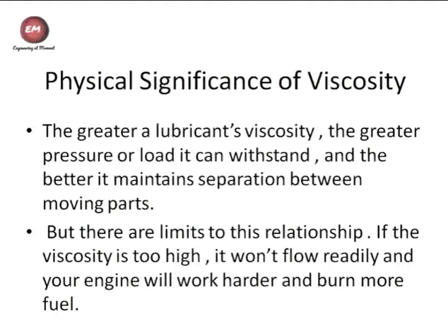And now we come to the physical significance of viscosity. As we know, the greater a lubricant's viscosity, the greater pressure or load it can withstand. So viscosity is important as the fluid withstands pressure and loads, and it is used to maintain a separation between the moving parts of machinery.